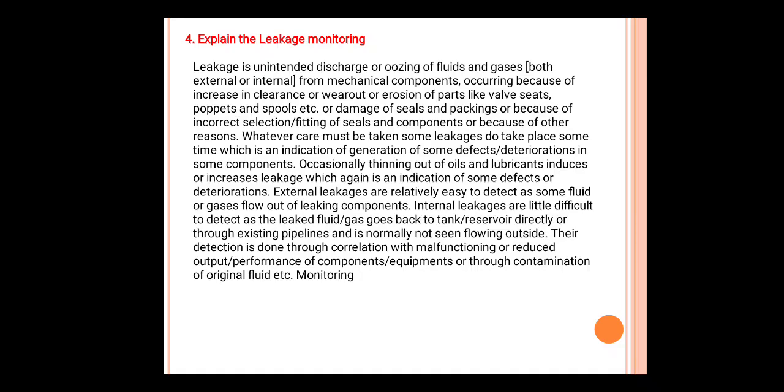Damage of the seals, packaging, or incorrect selection and fitting of the seals and components, or other reasons, may cause leakages. Whatever care is taken, some leakages do take place sometimes, which is an indication of the generation of some defects or deterioration in some components.